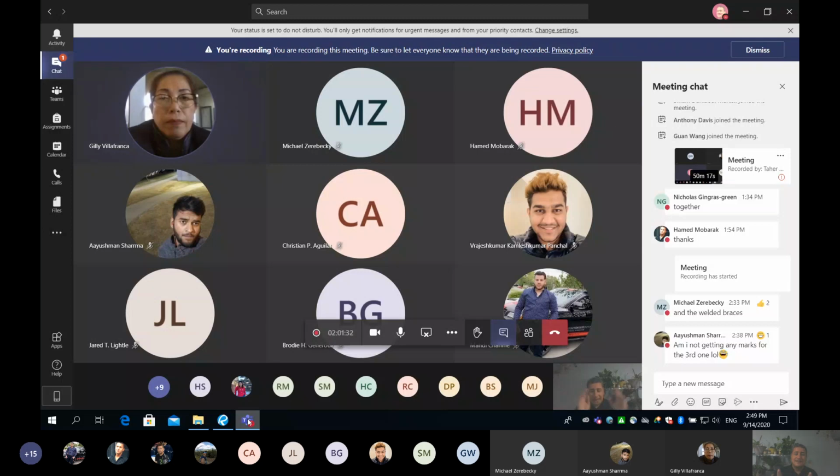Guys, which means, again, maybe you're not following. If I don't want to save any amount of rebar, then I take the maximum, design for the maximum, and put it all along the beam. If I want to save on my design and save some material, in this case, I'm going to see what happens to the moment along the beam. This is illustrated by the parabola. So I get another moment and I try to save on the rebar. So I have to design more than one section. This is time consuming, but you save some money.